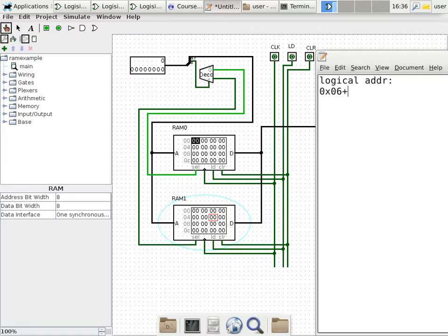Well, it doesn't tell you directly, but it does give you a hint, because it tells you the width of the address bus. What is the width of the address bus? 8 bits, okay? So if you have 8 bits to specify the address, how many unique locations can be identified? 256, because it is 2 to the power of 8.